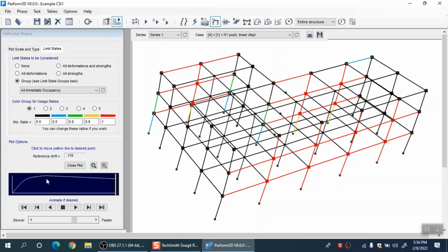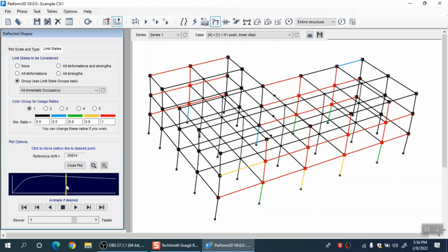Now we can use this exercise to calculate the seismic demands approximately also, right. And the idea is that if we know the roof displacement which the future earthquake will produce, we can push our structure up to that displacement, and the forces and displacements and all the results, all the damage up to that point are actually the seismic demands, right.